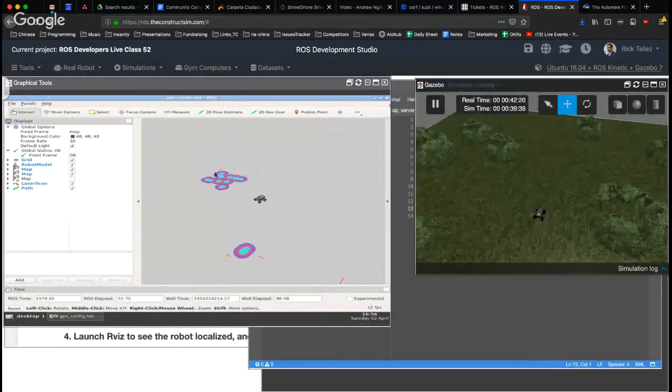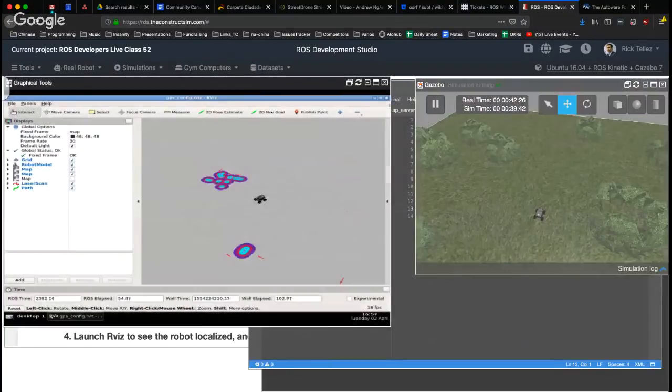And now, for example, let's tell the robot to go to one place around here. How do we do it? You select here a navigation goal, click on it, and then go to a location, and click without releasing, and then indicate the direction that you want the robot to face when it has reached the location. So for example, reaching here.